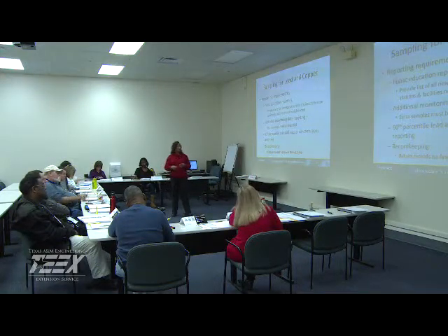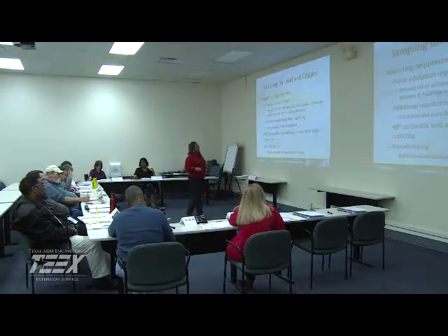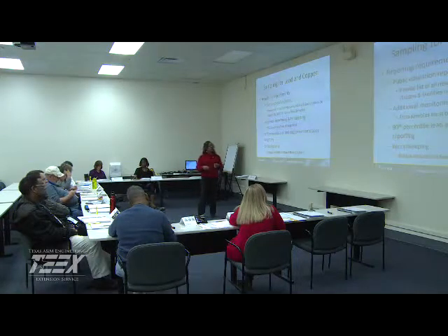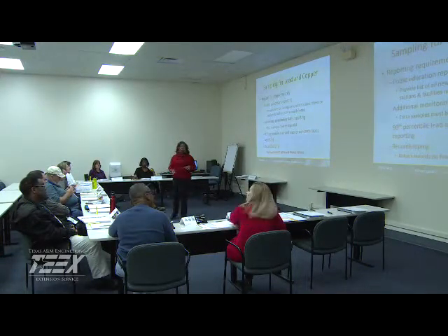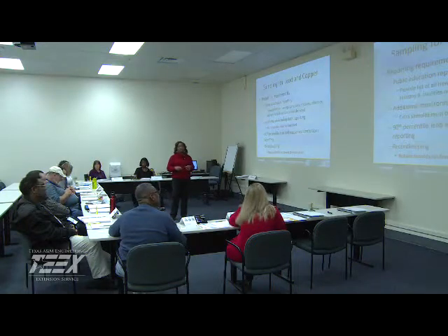We're going to report the 90th percentile, and again, make sure that you keep good records. If it's not written, it wasn't done. All record retention for lead and copper must be retained for a minimum of 12 years.